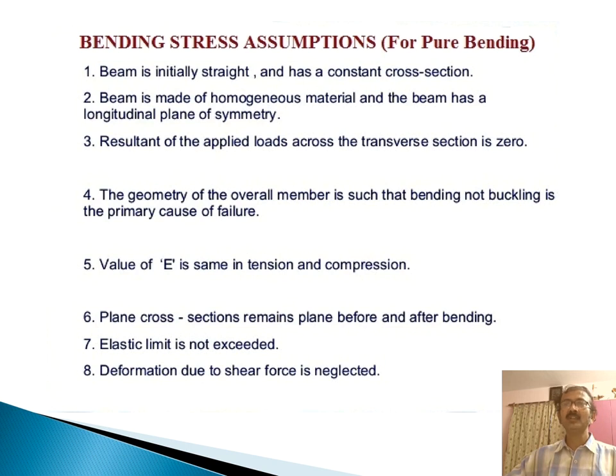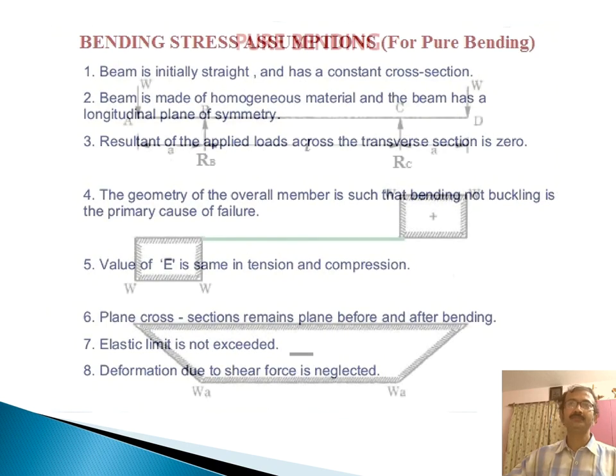Number six, plane cross sections remain plane before and after bending. Number seven, the elastic limit is not exceeded. And number eight, deformation due to shear force is neglected.